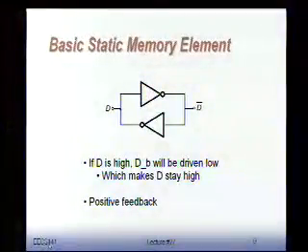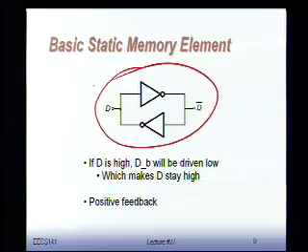So let's talk a little bit about SRAM. Let's ignore all the other memory types for the time being, and let's think about what it takes to build a good memory cell. Okay? Static memory, we know everything about it. We've talked about it when we talked about flip-flops. There's no difference. A memory cell looks like two cross-coupled inverters.